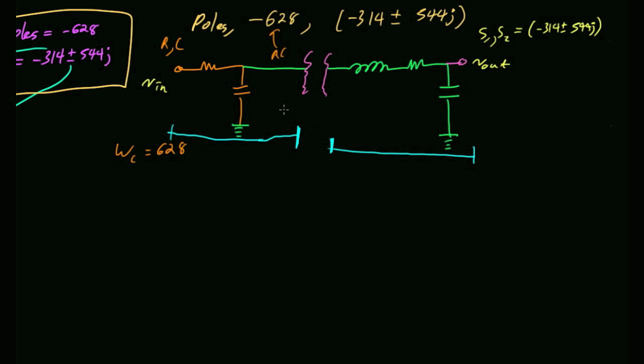When you design this first circuit, you're making an important assumption, which is that all the current that goes through here does what? Goes down, right? Our ability to pick R and C to give you this value depends on this current being true. As soon as you do this, some of the current that goes through that resistor is going to head that way. Meaning that this guy will still be a low-pass filter, but it's going to be a bear to figure out exactly what his characteristics are, because it's going to be very complicated to tell what goes where.